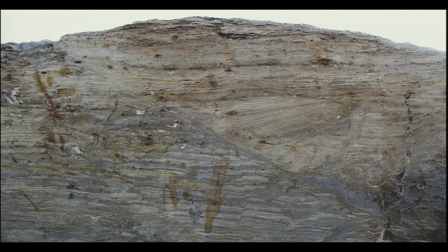So, if we just put a line here, or maybe later on I will remove the line, then what we see is this goes somewhere here, and then there is a line here where this part and this part do not match, because what we have understood until now is that the sediments will be horizontally stratified, but there is some break here which indicates that there is a displacement. And if you carefully see along this line, we are having what we call microfaulting. So, this layer is sitting here. There is a very fine line which goes here like this, okay. And then there is another one which goes here.